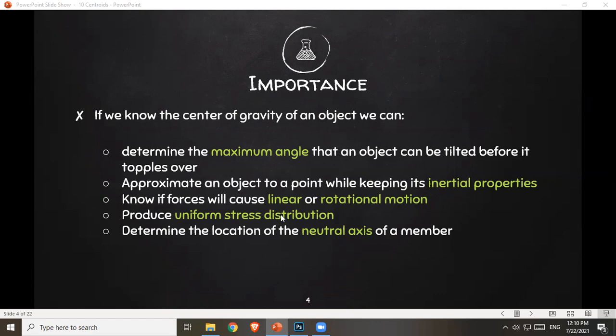If you had this topic in statics, remember, whenever you have an eccentric force, eccentric forces are forces not acting on the axis of your member. Whenever we have an eccentric force, it's beneficial to move it to its axis. When you do that, you create a normal force or an axial force and a moment. So if you remember that from your statics.